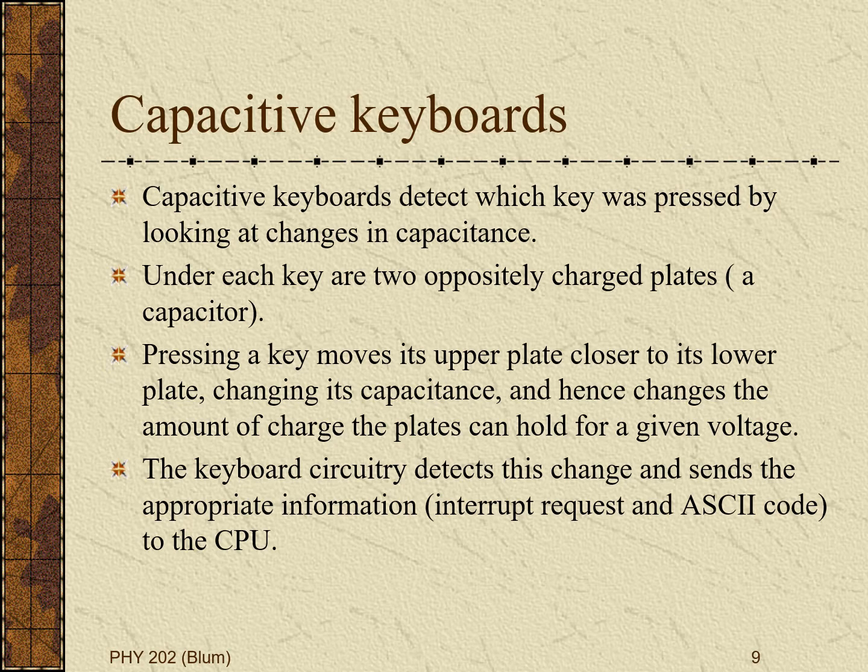These dependences of the capacitance, especially on the distance between the plates, allow capacitors to play certain roles in computers. Let's take, for example, a capacitive keyboard. Under a key you have two plates of a capacitor, and the physical act of pressing a key changes the distance between those oppositely charged plates. You are changing its capacitance, changing one of its electronic properties, and therefore it is electronically detectable. So I'm taking a physical thing, a person pressing a key, and turning it into an electronic thing that will be detected by the computer, and so we can detect which key was pressed.